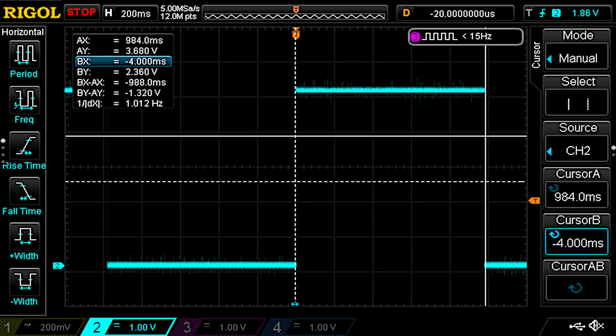Frequency counter in the scope doesn't work below 15 Hz, so all I have is the cursor measurements. Certainly not that accurate, but the 1 second interval seems to be in the 980 millisecond range. Now if I needed closer than this, it would be time to move to a crystal oscillator. This 32 kHz oscillator is not going to be that stable over voltage or temperature. That will be something to test, I guess.